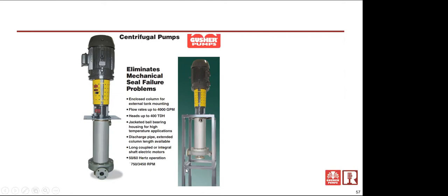You eliminate all the seal failure problems, and pump people tell you that 85% of the time that a pump is pulled for repair, it's pulled because of a leaking mechanical seal. It's the first thing that fails. Generally, when they replace a mechanical seal, they'll replace bearings and stuff like that as well, but those generally are not worn out as soon as the mechanical seal fails.